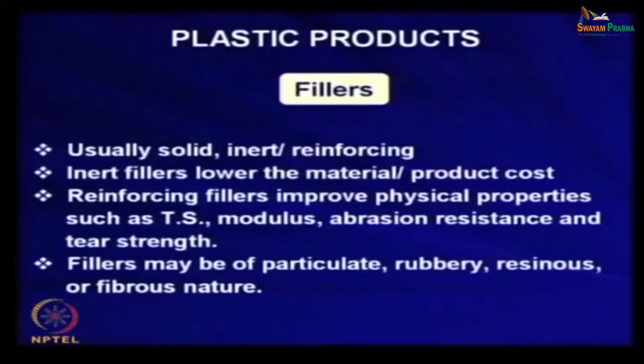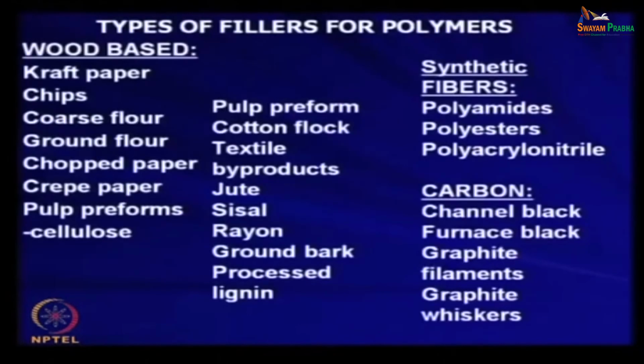Fillers may be particulate, rubbery, resinous or fibrous in nature. Then we will say it is a particle filled composite, it is a filler reinforced rubber, it is a polymer reinforced composite, resinous filler or fiber reinforced composite. Now, look, a huge number of examples can be cited for different types of fillers for polymers. This is wood based, you see, wood based